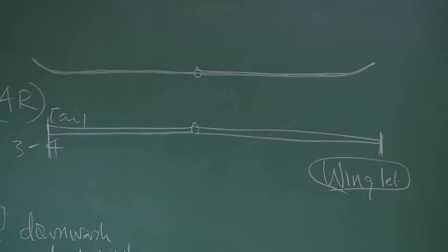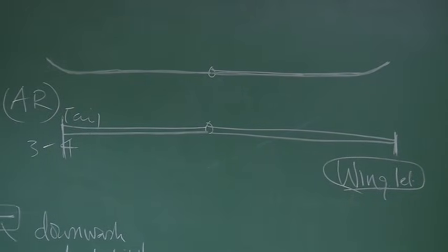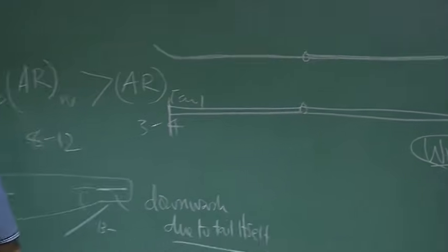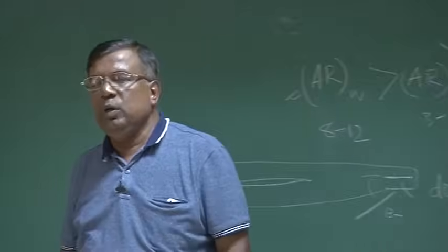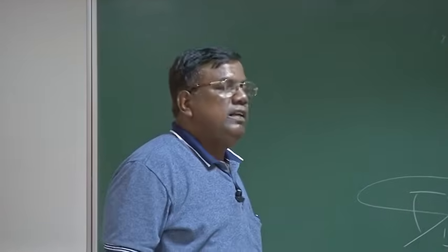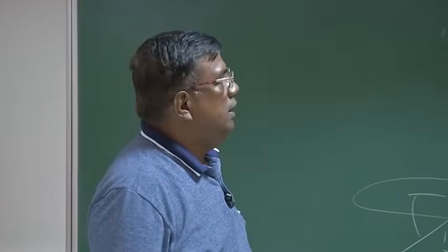The only problem of such a high aspect ratio wing and this sort of configuration is they become very sensitive to wind. That is why whenever we launch our glider, if there is appreciable wind, we will not really go for flight that day, because it becomes very, very sensitive to wind, right?